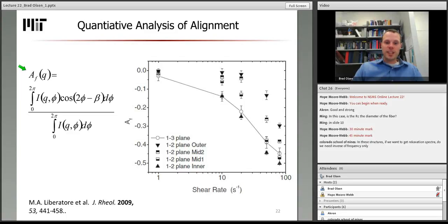But simply saying that each inverse frequency gives a characteristic contribution to the relaxation spectrum, it's not quite so simple, because the relaxations at every different characteristic timescale all become mixed together in the real material. And so this requires basically a fitting type of approach rather than simply a direct computation from the raw data type of approach in order to extract that spectrum. Hopefully that does a reasonable job of answering the question you were meaning to ask.